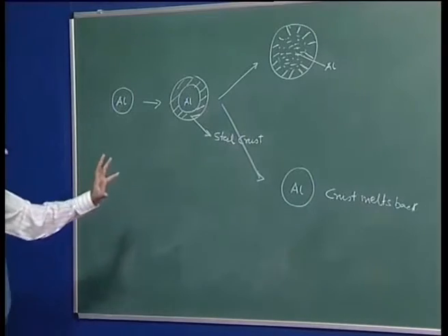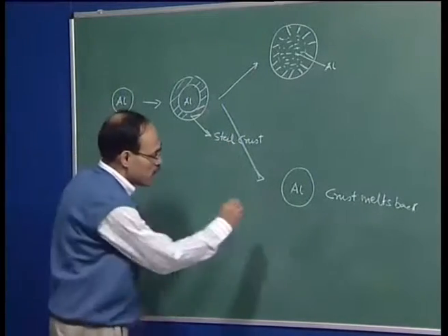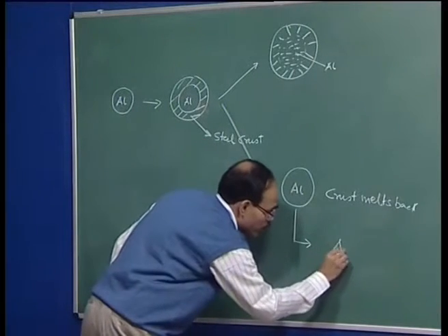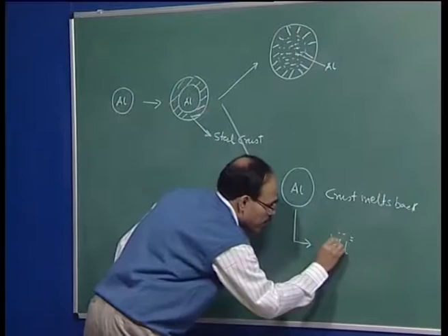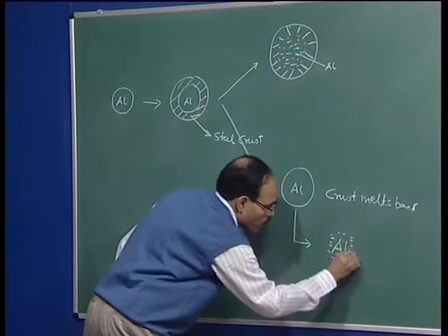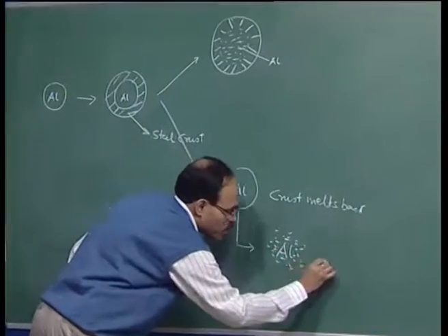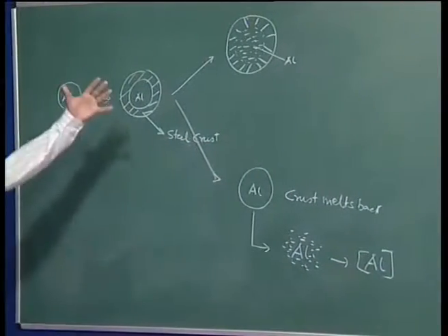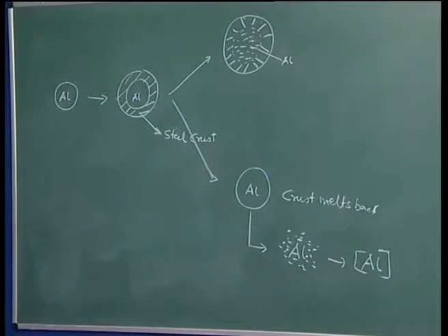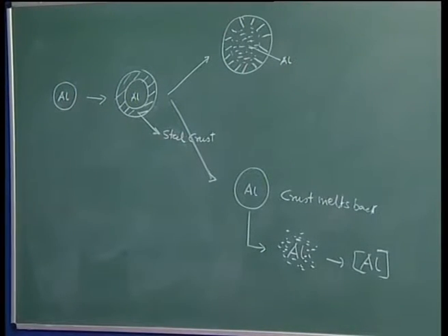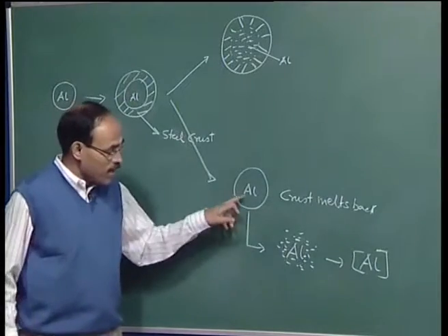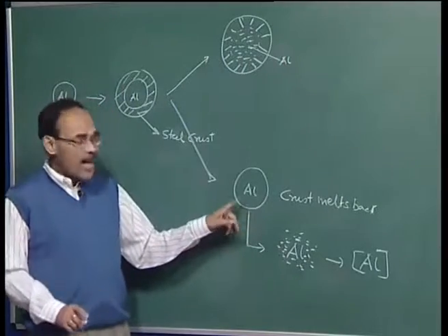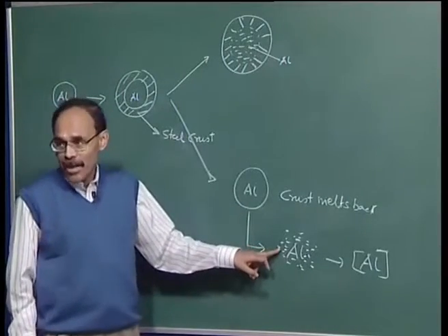But in any case, if it happens like this, then the aluminum will become aluminum liquid again, and then we can see that it is going to go to aluminum in the dissolved state. So these are basically the ways a solid projected into steel is going to behave. Now, this particular step I would like to draw your attention to can only happen provided the addition has a melting point which is lower than the bath temperature itself.